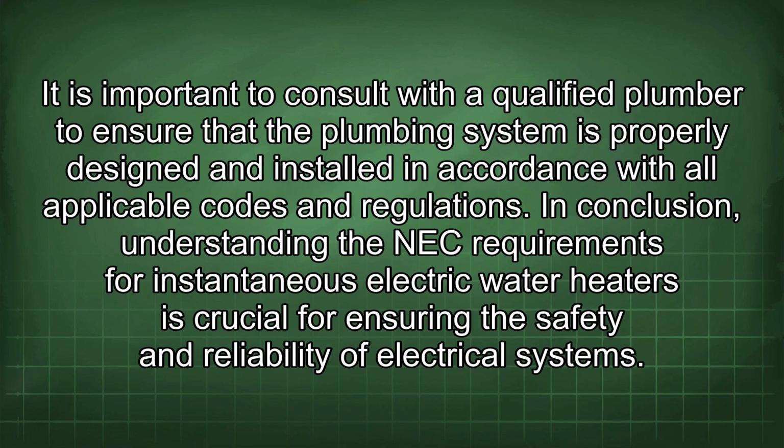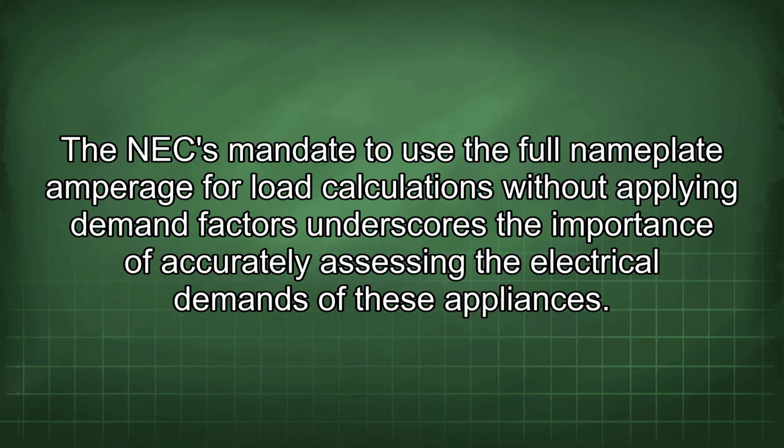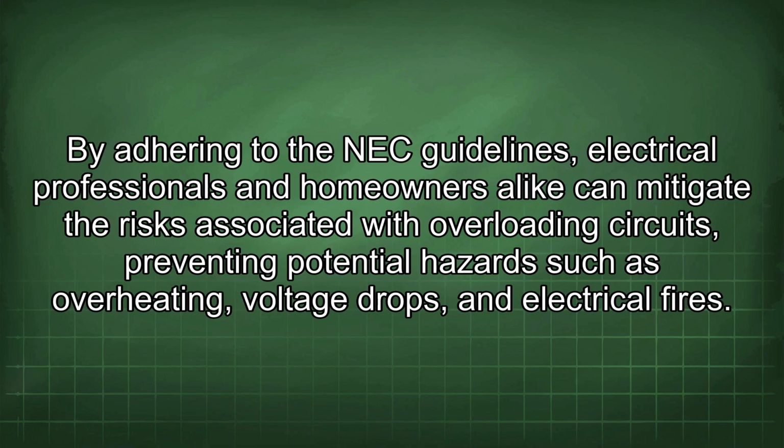In conclusion, understanding the NEC requirements for instantaneous electric water heaters is crucial for ensuring the safety and reliability of electrical systems. The NEC mandate to use the full nameplate amperage for load calculations without applying demand factors underscores the importance of accurately assessing the electrical demands of these appliances. By adhering to the NEC guidelines, electrical professionals and homeowners alike can mitigate the risks associated with overloading circuits, preventing potential hazards such as overheating, voltage drops, and electrical fires.